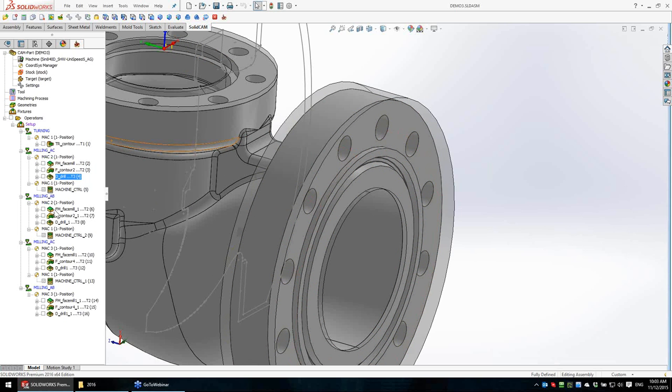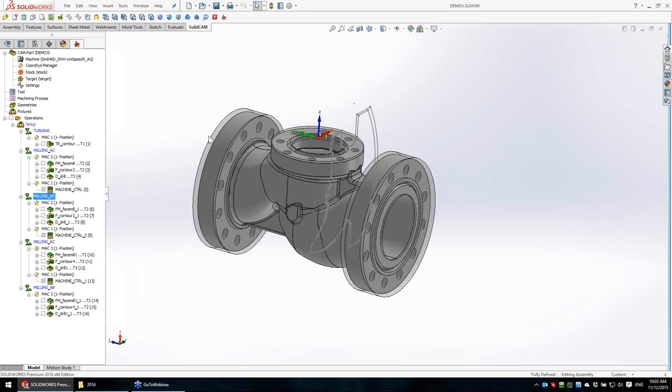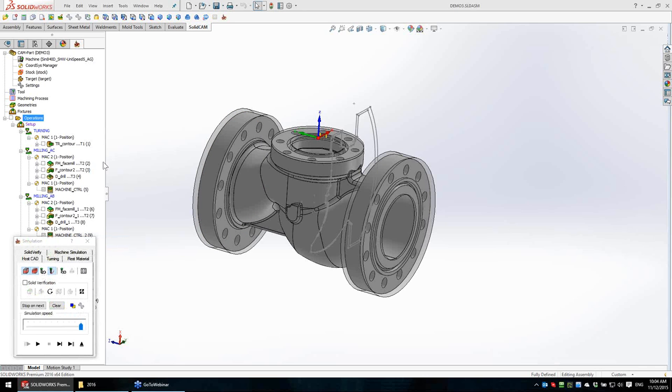Now to save time, I copy the operations and select another sub-machine. Here I work with A and C, here I work with A and B. Between them, the C axis remains uncontrolled, so I need to reset the C axis with NC0 in order to continue to work with A and B. The same for the opposite side: the same operations, a face mill, contour, and the drill, starting with A and C kinematic, resetting, sending the C axis to 0, and continuing with the sub-machine with A and B, head table kinematic. Let's see how it's working.